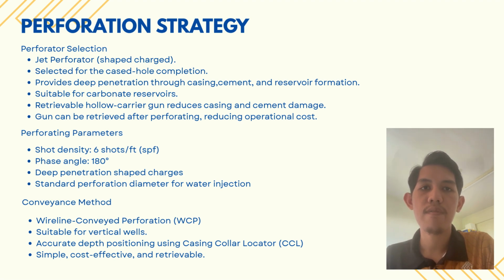Because the well is vertical, we choose wireline conveyed perforation, or WCP. This method is simple, economical, and provides accurate depth positioning using a casing collar locator, or CCL. Another advantage is that the perforating gun can be retrieved after the operation.